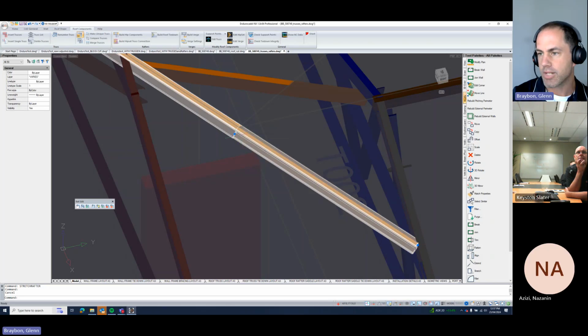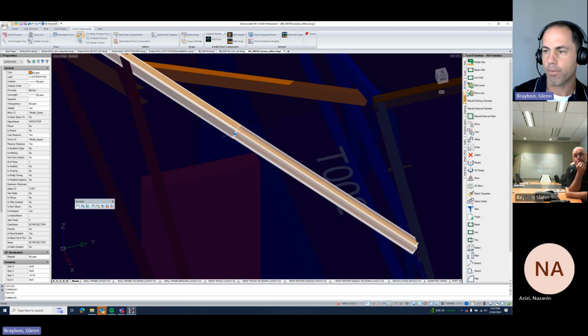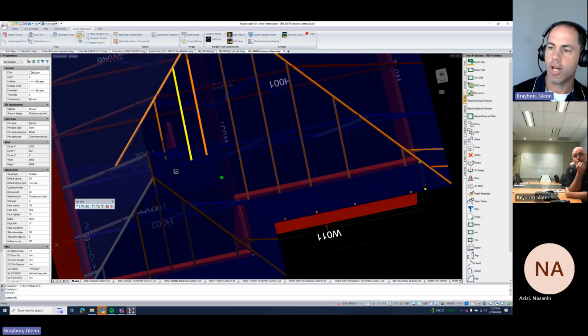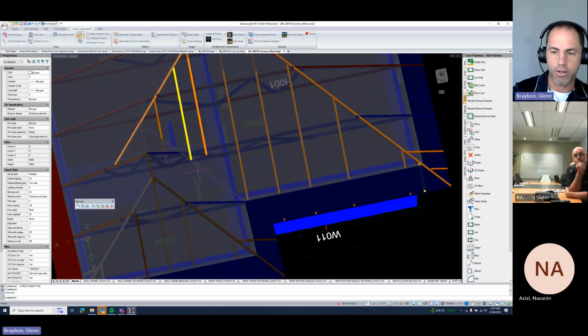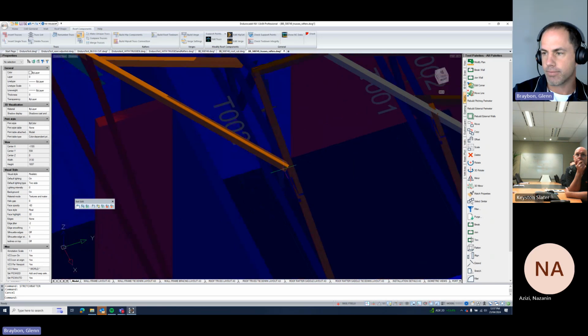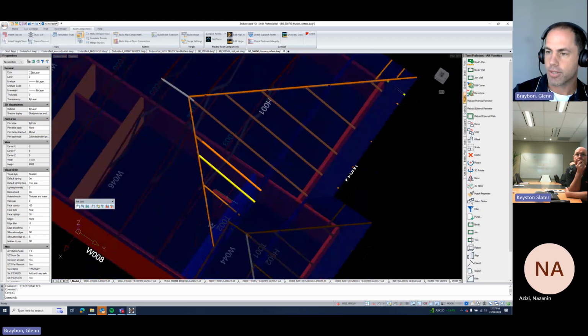There isn't, but that's exactly what you spoke about the other day, that we need to consider when we're making upgrades to the rafter menu or the rafter connection details. Today we're focusing on what the roof shape and roof components can do. Those suggestions are great and they need to keep coming, but that's an improvement on top of what EnduroCAD can do, as opposed to what we're doing at the moment, just trying to get NX to do what EnduroCAD can do. But completely agree. If we get a bent tab, probably the outside boxed one, that can fold around somehow and screw into that top cord to create that box.